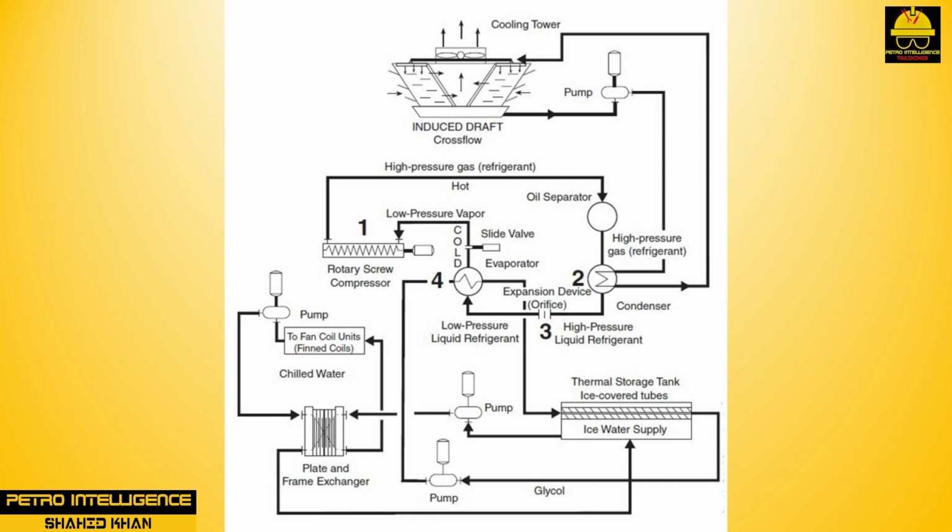Propylene is a good example of such a liquid. Its boiling point at atmospheric pressure is -54 degrees Fahrenheit. Propylene is normally a gas, but using a compressor can liquefy it. In compressing any gas, work is done, and heat is generated in the gas. In compressing propylene, we add heat to the gas and raise its temperature. Raising the temperature allows us to cool the compressed gas with water, and in this manner the propylene is liquefied. At this point, we have a supply of liquid at elevated pressure and at about room temperature.